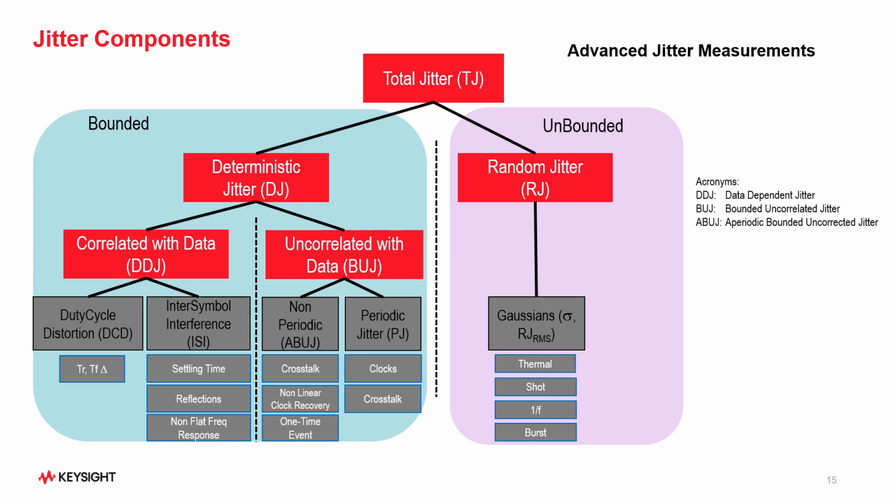On the top right, you will see the total jitter, where we sum all the jitters together. This is the total jitter, but they can also be grouped into two main categories. On the left side, one can see the bounded category. It means the jitter introduced by these components is limited, so these don't increase over time.